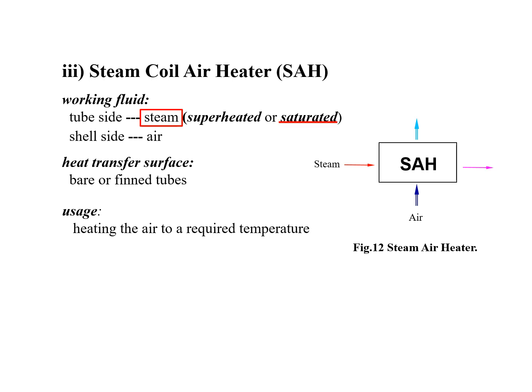Finally, all the water is vaporized into water vapor, and the water vapor no longer contains any liquid water, which is called dry saturated steam. If the dry saturated steam is heated further, its temperature will rise again and exceed the boiling point at this pressure, then the steam is described as superheated.